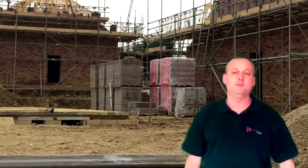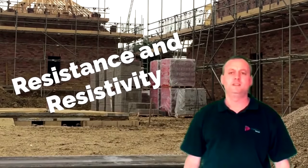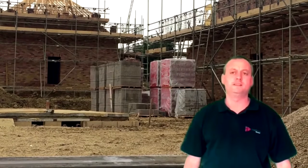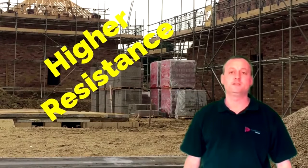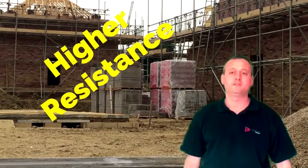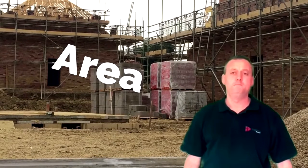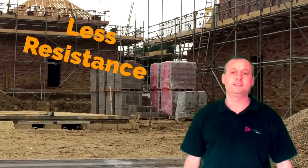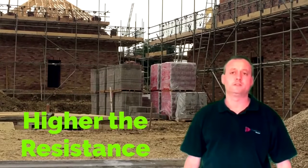After recapping our Ohm's law notes, we went on to look at resistance and resistivity, and we said the resistance of a conductor will be affected by the length of the conductor. Longer conductors have higher resistance, so shorter conductors have less resistance. The cross-sectional area will affect the resistance of a cable. The bigger the cross-sectional area, the less the resistance. The smaller the cross-sectional area, the higher the resistance.